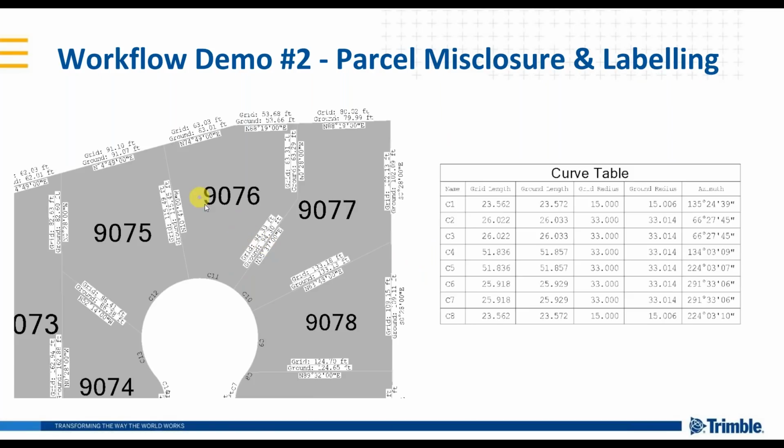Anyhow, the important thing to note here is that we have custom parcel labeling in TBC. We have our grid and ground distances listed. Some people use grid, some people use ground. Now you've got the option to choose between them. And we have our bearings labeled. Sorry, the Canada rubbing off of me. They're all rounded to the nearest minute here. In TBC, you can select to round to the nearest second, 5 seconds, 10 seconds, 20 seconds, 30 seconds, almost any angle that would make sense to you. That way you don't have to over-represent the accuracy on your deliverable.